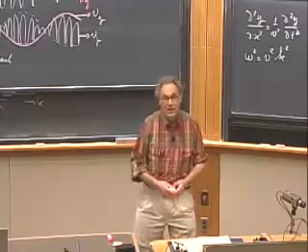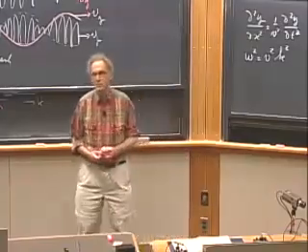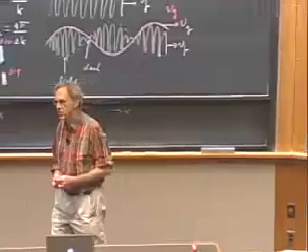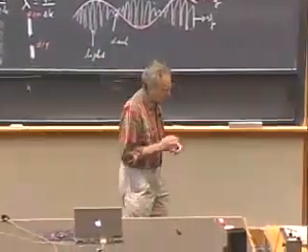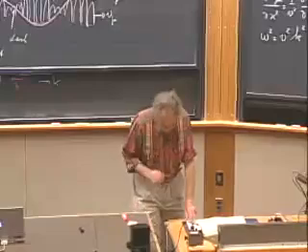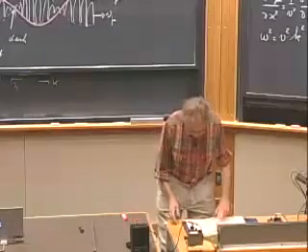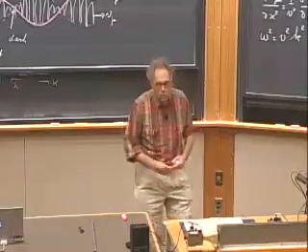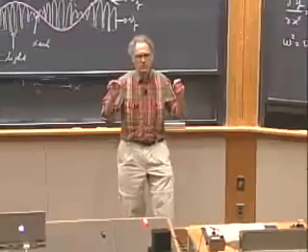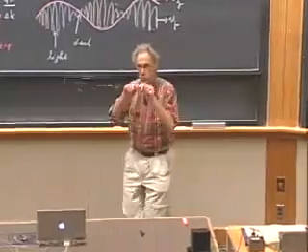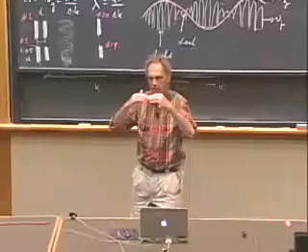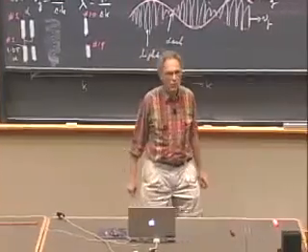However, there is something that we did not take into account, and that is the stiffness of the wire. Imagine for now that the tension is 0. So you take a piano string, or the string from a violin, and assume there is no tension at all. You take it in your hand and you bend it. There's no tension, you just bend it. It wants to straighten out. And that's the result of stiffness.